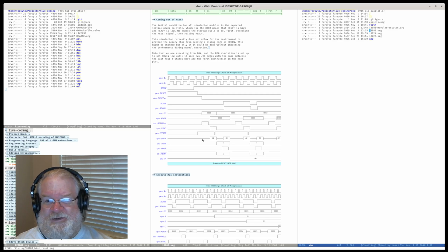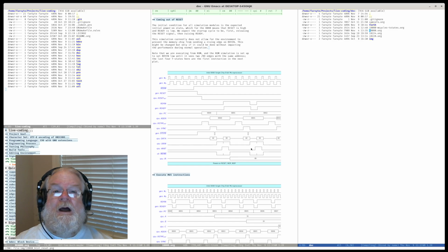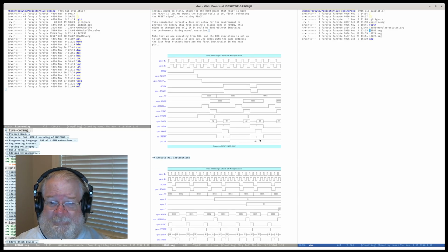So once we come out of reset, we get this normal pulse of operation where the CPU sends out a sync pulse, we get a status strobe, there's the address of the opcode, we end up getting a fetch. Now, in this case, we're reading from a ROM, so I am enforcing one wait state during all the reads. We are not handling wait states during writes or during I/O writes. So there's another way we're not quite complete.